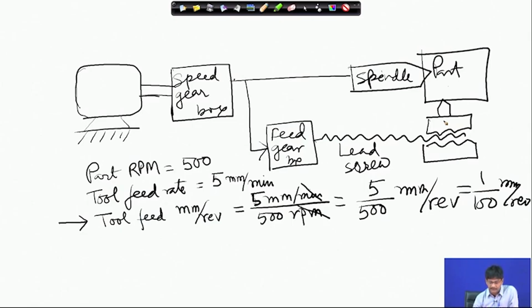This is how the lathe architecture has been contemplated. Okay. So, let us see whether tool feed changes or not. I multiply the output of the speed gearbox by 2. That means I do something inside the speed gearbox, just like changing the gear of an automobile, I can get different speed outputs. In the same way, I multiply the output by 2.